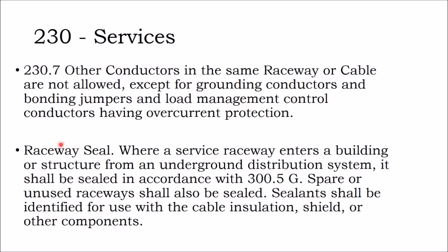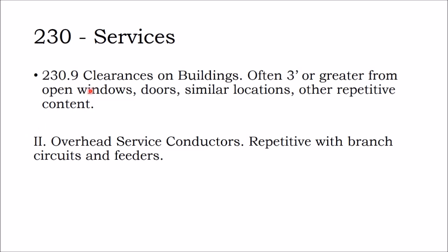And then we talked about the raceway seal earlier. Clearances on buildings, often 3 feet or greater from open windows, doors, or similar locations. If this feels like deja vu, you're not going crazy. This is the same requirements for services as we saw for feeders. And remember, services is a more specific kind of feeder, and it's coming a little bit later in